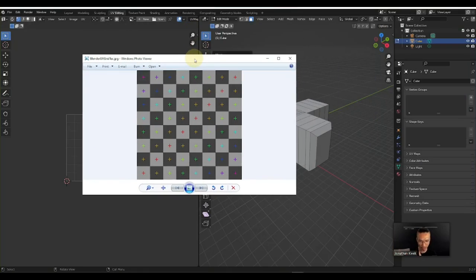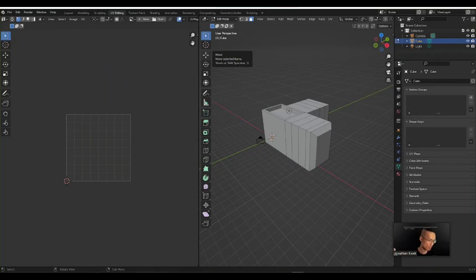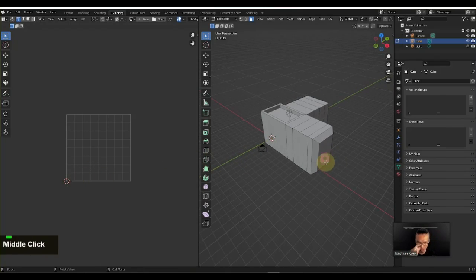And what happens outside of this UV space? What happens on the outside of this UV space is that the texture then repeats itself, sort of like a Pac-Man map. So you start all over again from 0. So if you're out here, then really you're somewhere back here. You're displaying the same part of the texture somewhere back here. So very important to keep this in mind.